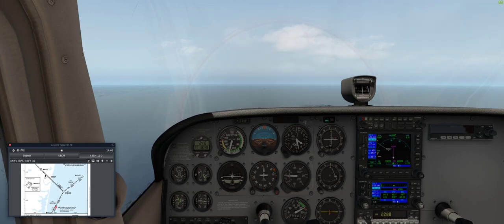I guess what I'm saying is it's going to work exactly like you would expect it to work if we were locked onto an ILS approach, except it's not an ILS radio signal that we're using. It's an RNAV approach that's pre-mapped out with altitudes and waypoints to align you on the runway, and from your perspective, it will function about the same.